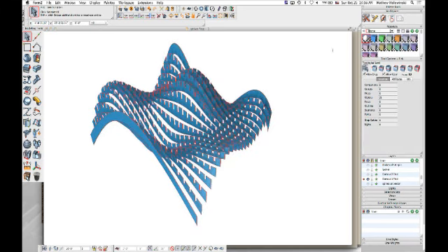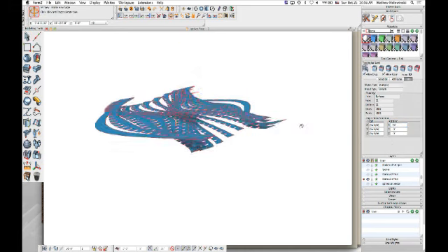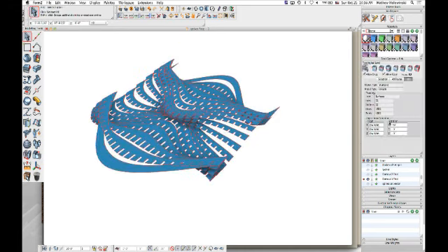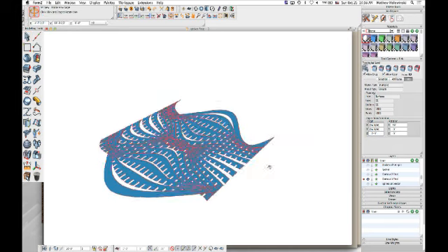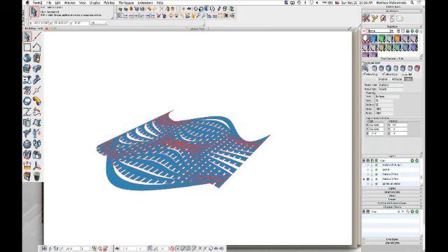And one thing that you can do is anytime you want to get information about objects, you just grab the objects, you look in tool options, all the stuff is always over here in the tool options palette. One of the things is the information about the object. So I can have all these objects and say, let's rotate them all 90 degrees by the X. So they're all lying flat, like that. I'll move them so that the Z equals 0, and boom, now they're all laying flat on the XY plane here. I have the plane turned off. Turn that on there. There it is.